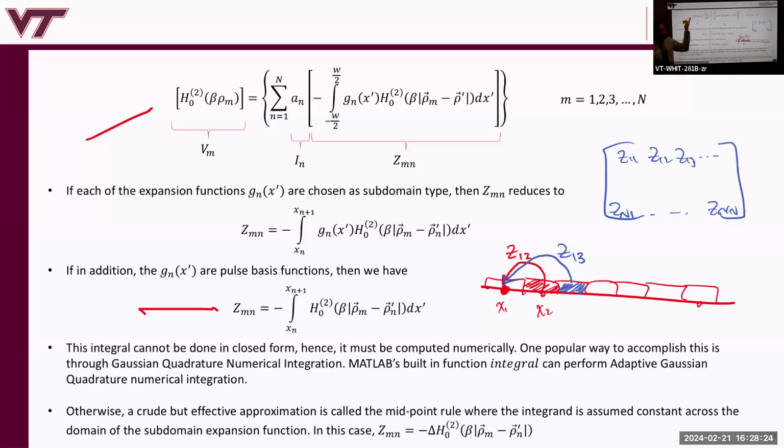So each row of the matrix equation, or this equation evaluated for all different n, but at each m, at m equal to 1, is saying the boundary condition at that point has to be satisfied, which means the radiation due to all this current added up at that point, giving you the true total field, has to be set equal to 0, right? Okay. Then you move to this point and you do the same thing. Find the radiation to here, there, and so forth, right?